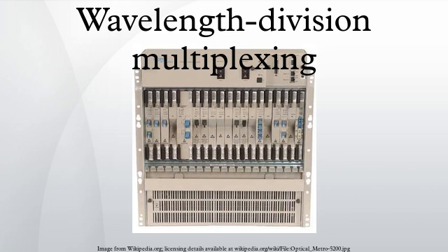Conventional WDM systems provide up to 8 channels in the third transmission window of silica fibers around 1550 nm. Dense wavelength division multiplexing uses the same transmission window but with denser channel spacing. Channel plans vary, but a typical system would use 40 channels at 100 GHz spacing or 80 channels with 50 GHz spacing. Some technologies are capable of 12.5 GHz spacing. New amplification options enable the extension of the usable wavelengths to the L band, more or less doubling these numbers.